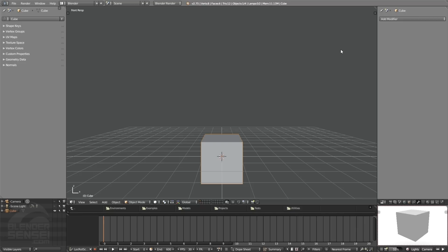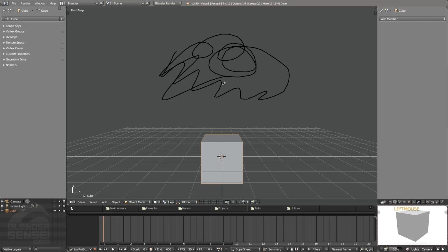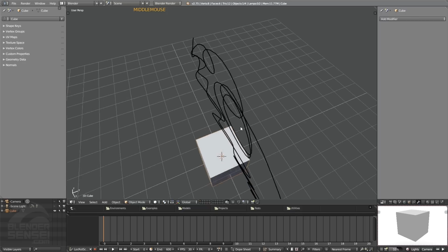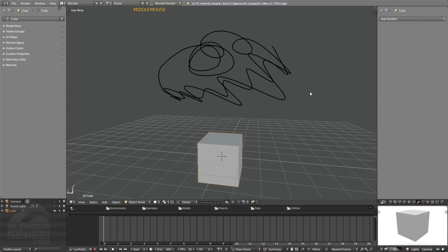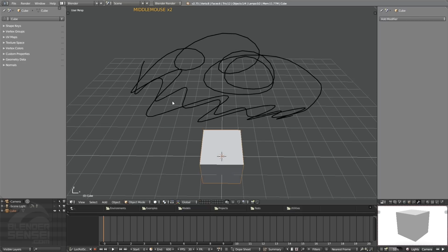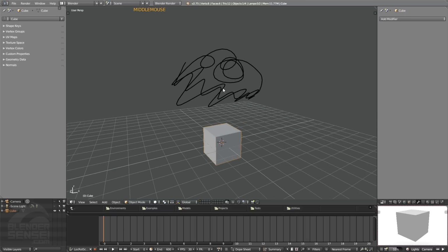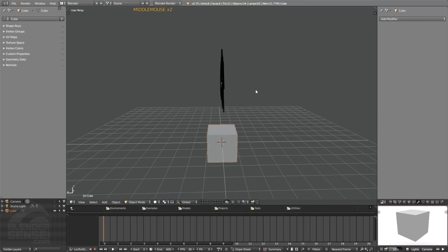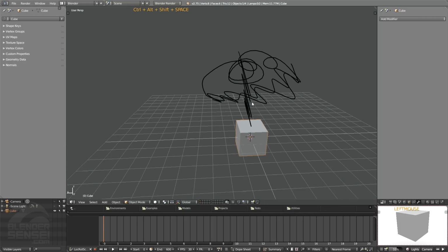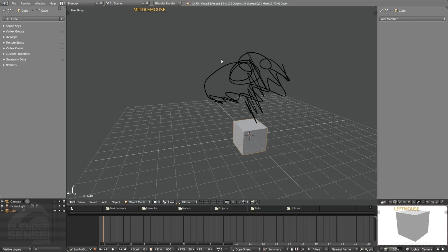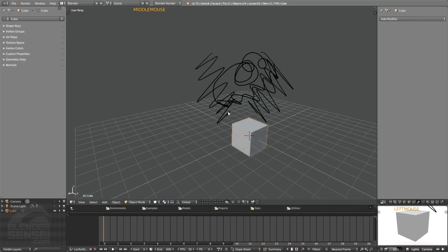So the easiest way to use the grease pencil is just by holding down the V key on your keyboard, then just start drawing. And we immediately have these strokes. And so if I then go to rotate my screen, we see that our sketch has been manifested in the middle of the screen. So I could rotate the screen around, hold V, draw some more with my left mouse button or just by clicking down with my stylus or my tablet.